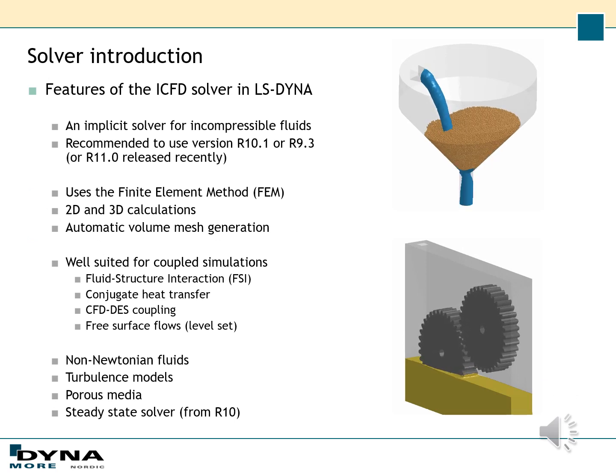So the ICFD solver is an implicit solver for incompressible fluids, and recommended LS-DYNA versions to use are either version 10.1 or 9.3, or you could also try the new version R11 that has been released recently. The solver is based on the finite element method, and it supports both 2D and 3D calculations.